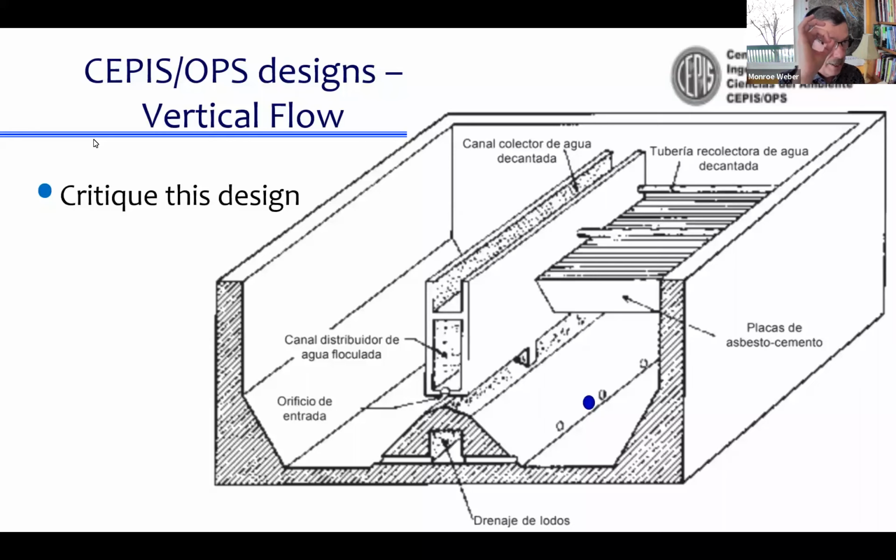The reverse, when you have a vacuum sucking, now the fluid that's entering that hole comes from everywhere. It sees this as a sink, and it comes from all around the vacuum, even from back behind the vacuum. It comes around and it goes into that hole from everywhere. So it's pulling air in from like a sphere. Air is flowing in spherically, like, I'm not using the right words, but it's all coming in like a sphere towards that center point. And that means that the velocity, as soon as you get just the tiniest distance away from the vacuum hose port, has dropped off tremendously.